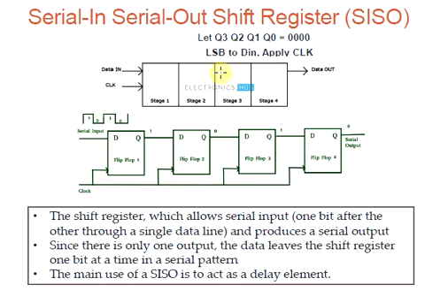And for the fourth and final clock pulse, the most significant bit will be given to D in, so that finally you will get the most significant bit here and the least significant bit here, and the final output will be taken out of this data output.